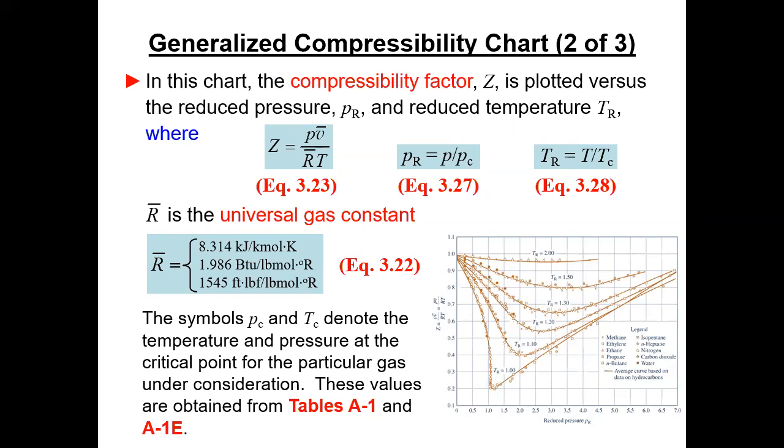Yeah, but on a molar basis. Normally we think about volume per unit mass, but when it's got the hat on it, it's volume per unit mole. So yeah, you need to think about it. When you get those things with hats on them, you got to be careful because you're going to have to use the molecular weight.